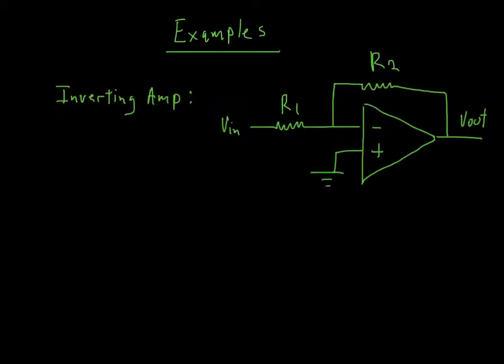What we're interested in here is the gain. And because there's a loop here going from the output back to the input, this will be closed loop gain. The open loop gain is something that's specified for the op amp. It's hard to calculate, it's just given with the circuit. However, the closed loop gain we can always calculate.